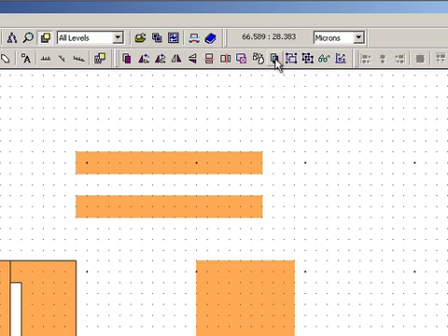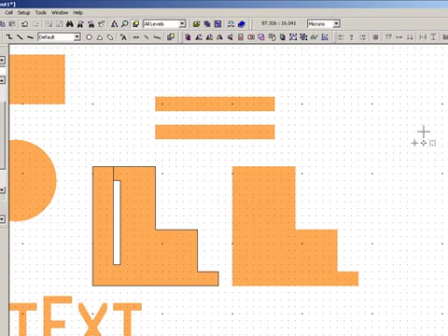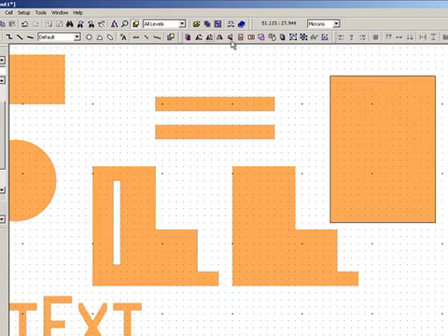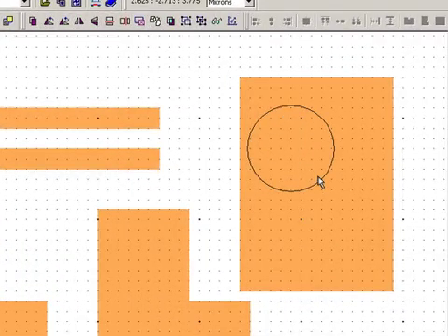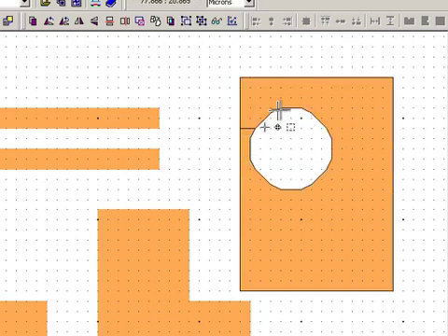There's another method using the Boolean operators that allows you to do a similar thing, and also some more advanced features. We'll come back to the Boolean operations in a little bit more detail, but just know that Nibble also works with curves. So if I wanted to nibble a circle out of this type of substrate, I can select it and nibble a circle out. Now do note that it's going to change it into a polygon, an approximation of the circle, and it doesn't look very pretty at this point in time. In a future video, when we discuss curves and circles, we'll explain how to work around this approximation of curves. So for now, we'll just leave it at that.